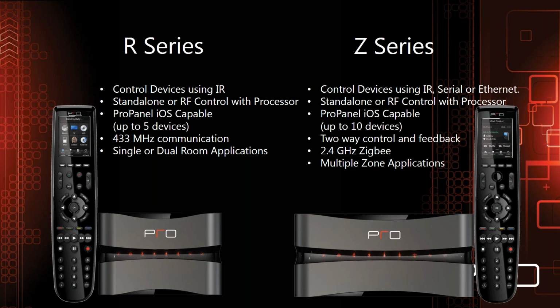Whether you're sending IR commands from the remote itself, or you're sending RF commands from the remote to the processor, and then the processor is sending IR out. But at the end of the day, on the R series, you're controlling your devices, your TVs, your receivers, lighting control, whatever it may be, you're controlling it with infrared. That's the major difference here, infrared on the R series. Now you can do, again, RF from the remote to the processor, and then send IR out from the processor. You can do any combination of sending IR from the remote, from the processor.